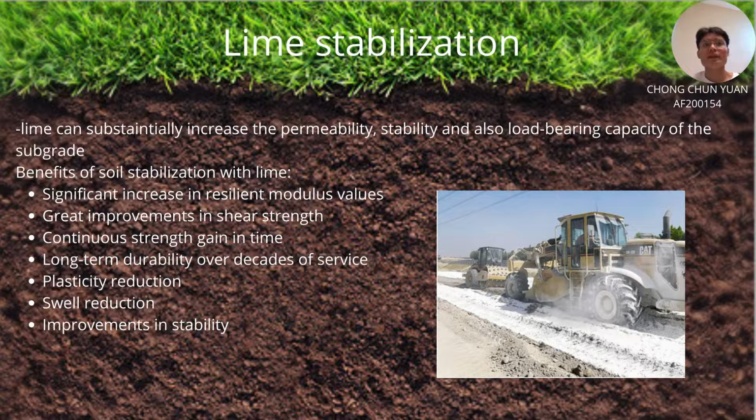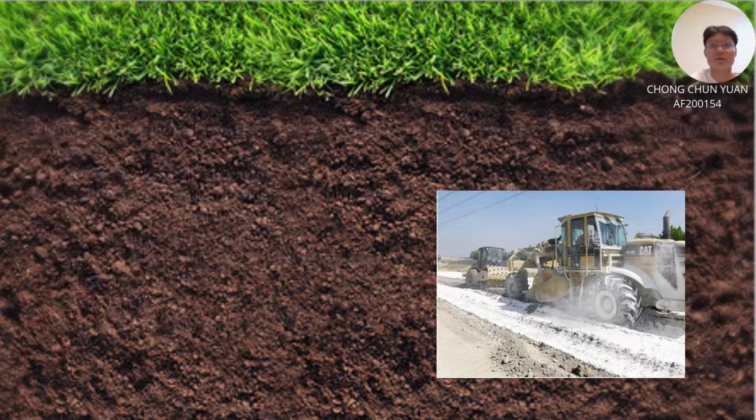Lime can substantially increase the permeability, stability, and also load-bearing capacity of the subgrade. The benefits of soil stabilization with lime are increased resilient modulus values, great improvement in shear strength, continuous strength gain in time, long-term durability over decades, surface plasticity reduction, swell reduction, and improvement in stability.